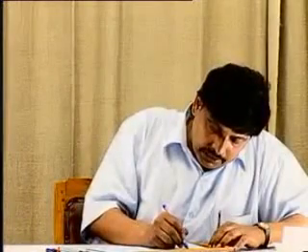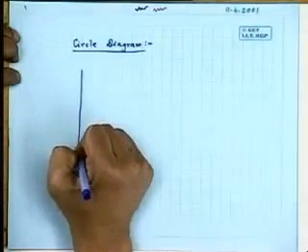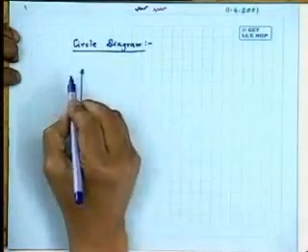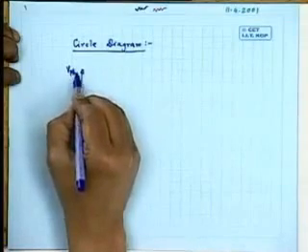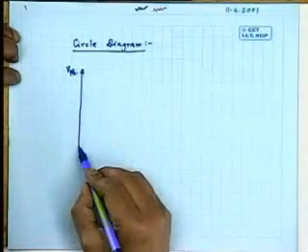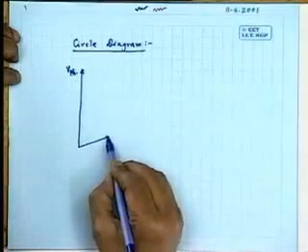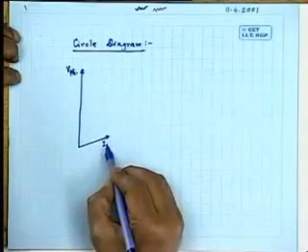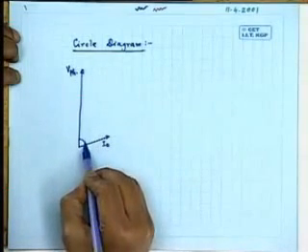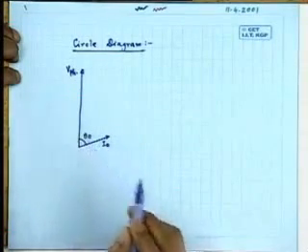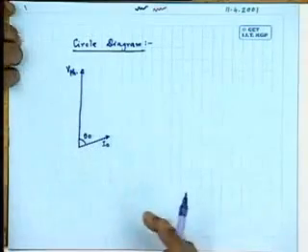Today we will complete the circle diagram which we started earlier. So just quickly remember that when you consider the stator impedance as well as core losses, if this is your phase voltage, then the circle diagram will look like this. This is your no load current, and the no load power factor angle theta, and this can be obtained from the no load phase.